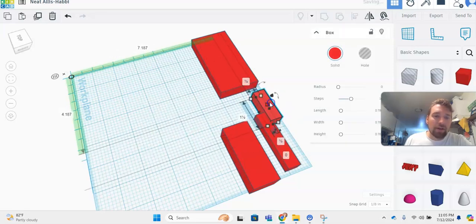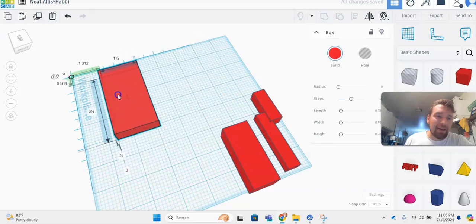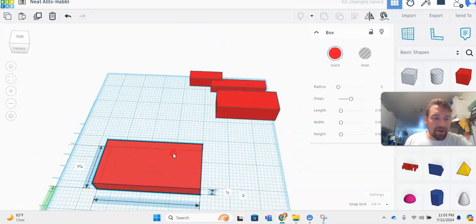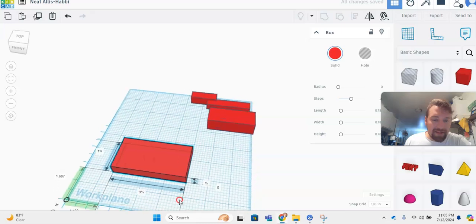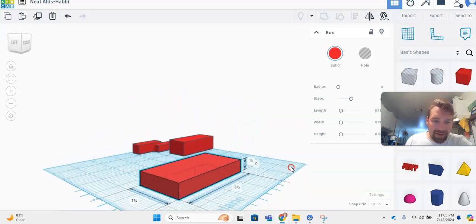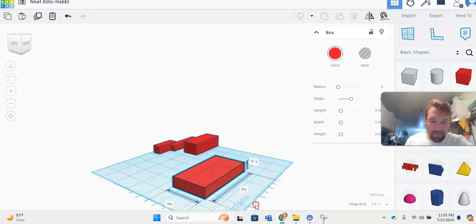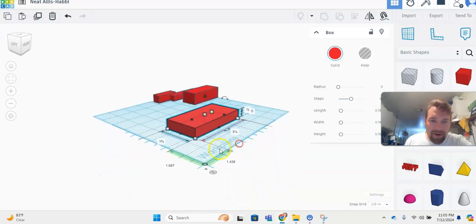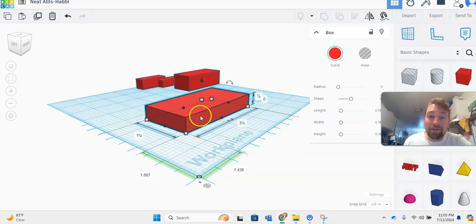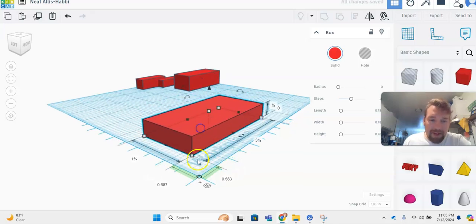So here's what's going to happen. Now I'm going to use my ruler to help me get everything lined up exactly the way it needs to be. So how about I start over here? Okay, there you go. That gives me a better view. Again, you've got to learn to play with the mouse a little bit. And I'm just going to type it in, and I want to set the corner of this block to be at the corner of my datum.